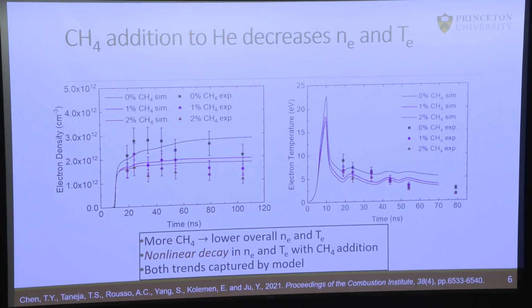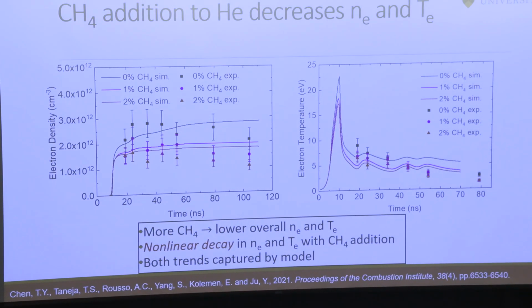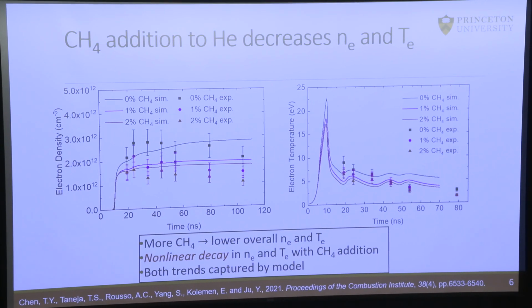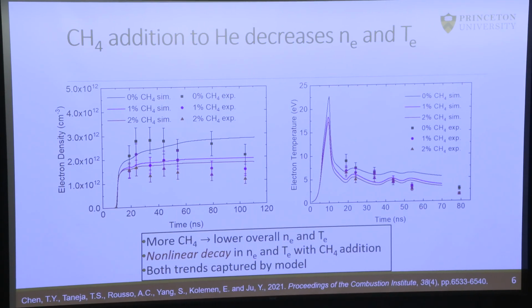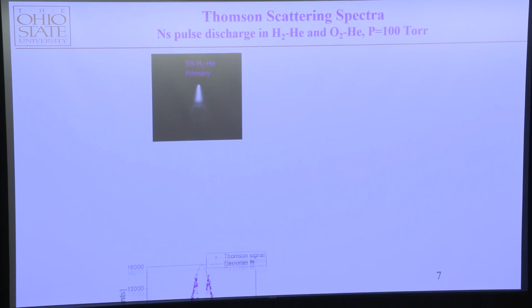So this is contradictory to previous plasma work. Plasma people always think that when you add some kind of reactant, methane or ammonia, into the mixture, the electron temperature is linearly affected. But our experiment shows that no, it is non-linearly affected. So that is a dramatic change in terms of UV. Just like when you put some hydrogen into methane, the ignition delay time does not change linearly. It is a non-linear change. Is that because of the plasma chemistry? The flame speed maybe changes linearly, but